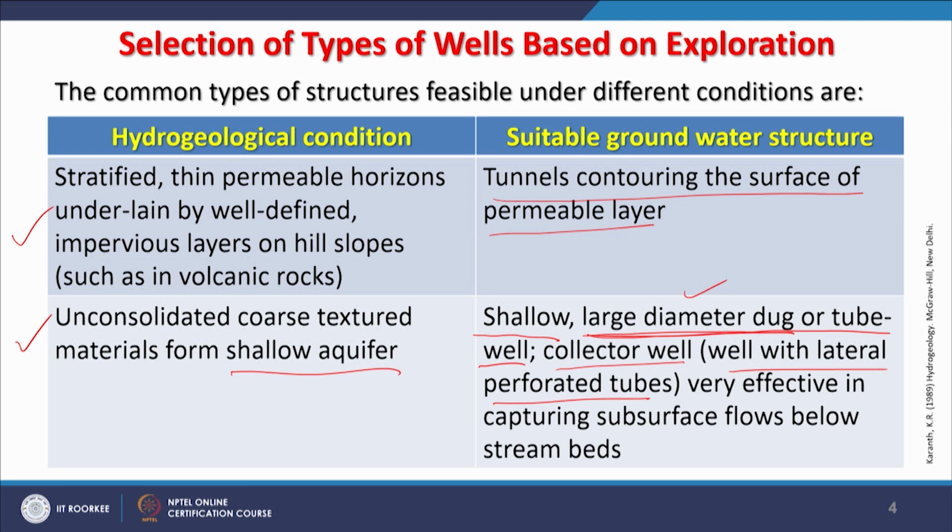Most of the people are going for the tube well or bore well and then installing a pump on it. So, in unconsolidated coarse textured material forming shallow aquifers, the shallow large diameter dug well, tube well or collector well is very effective in capturing subsurface flow below stream beds. In certain conditions, when you have a stream or some riverlets or rivers, these are also very good.